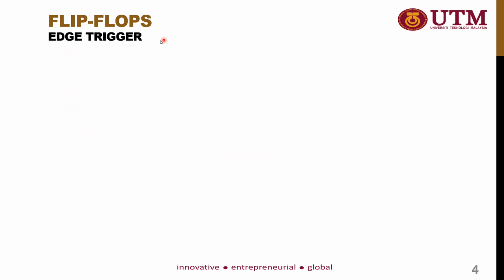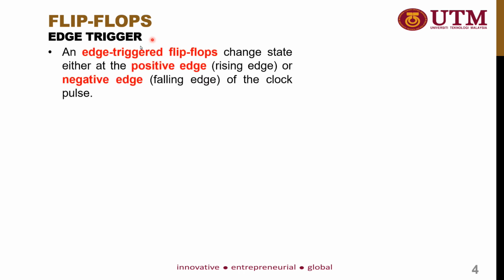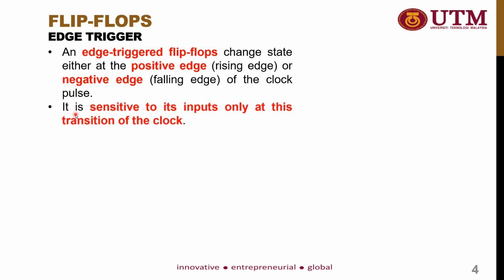So next is the term edge trigger. An edge-triggered flip-flop changes state either at the positive edge, the rising edge, or the negative edge, which is the falling edge, of the clock pulse. So it is sensitive to its input only at this transition of the clock.